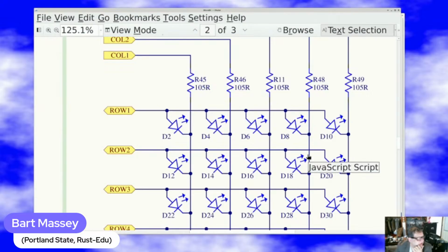So the point is, if I want to light up just one LED at a time, I set this row positive and all the other rows grounded. And then I set this column grounded and all the other columns positive, maybe. And when I've done both those things, this is the only LED that can light up. I can light up exactly one LED. So now we know how to do what we need to do for our program, right?